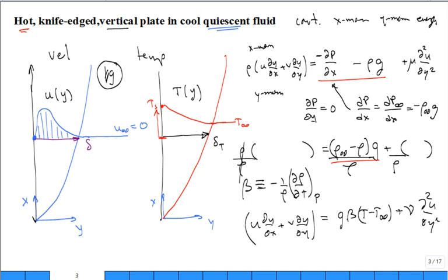So it's almost like magic. How did we pick up this g beta delta T term? That's the term that drives the natural convection flow. True? How do we pick that up? Well, it's a few steps, and we introduce that parameter beta.